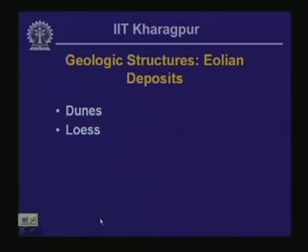Okay. Now, we have to consider geologic landforms that are due to the activity of wind, and we normally get dunes and loess. Loess is essentially fine grained, I mean silt size, particles blown by wind, and these are characterized by steep slopes. They are very susceptible to failure if they become saturated with water, whereas dunes are generally underlain by sand grain deposits.